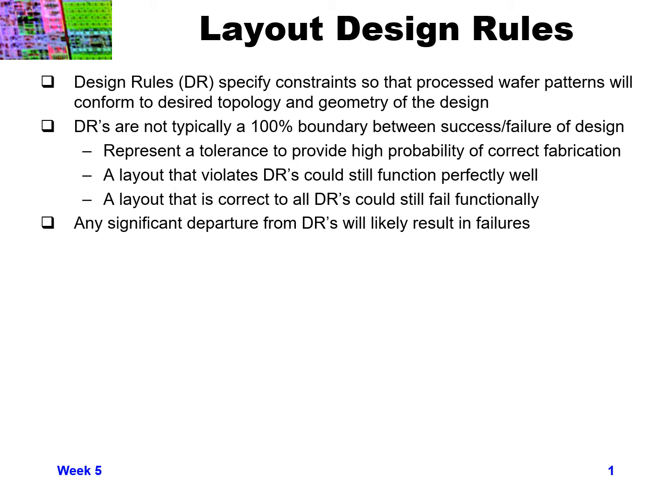So potentially a layout that violates your design rules could still function perfectly well, depending on how much you're violating the design rule and what type of rule you're violating. And possibly also a layout that is correct to all design rules could still potentially fail functionally. That might be a matter of a design rule that wasn't known before you started.